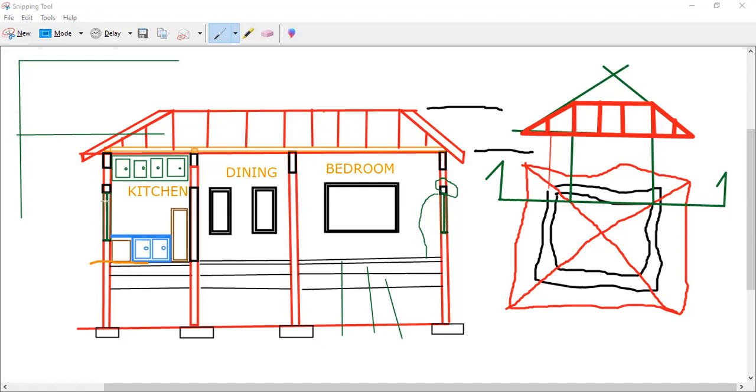I will then offset this 150, plus I think this question asks that you add some plaster on both sides, so this would typically be 170. So you'd offset that much. While offsetting, I strongly recommend that you use Through. To activate offset, you would type O, enter. Before you click, you click on Through or type T, enter.